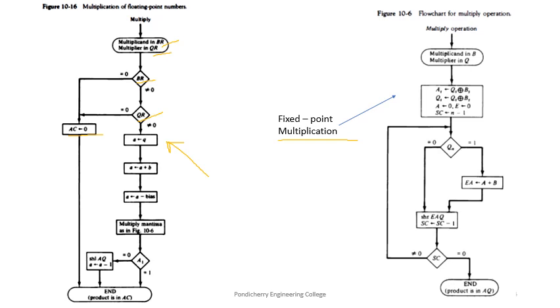In case both the operands are non-zero values, we proceed with the multiplication. Earlier we have seen that the multiplier is in the Q register, but if you refer to the register arrangement, the adder for the exponents is between the small a and small b registers. So here the small q content, or exponent of the multiplier, is transferred to small a, and then a and b are added, that is, the exponents are added and the result is shifted to a.